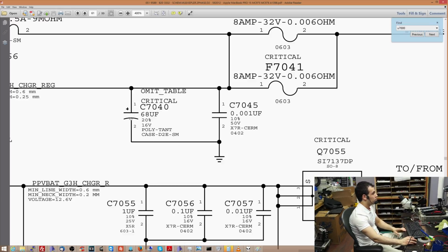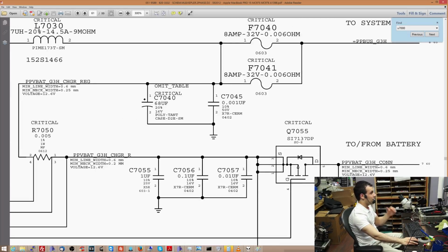Let's say that insulator blows or gets destroyed, and these two plates are now touching. This is not going to be blocking DC anymore. It's going to be allowing anything to go through. So all of this power, the 5 amps or whatever that is going here at 12.5 volts, is all going to be going to ground, and that is going to kill the circuit to high hell. So that is how a capacitor very commonly shorts to ground and causes the circuit to be what's considered shorted. That is what a short circuit actually is.